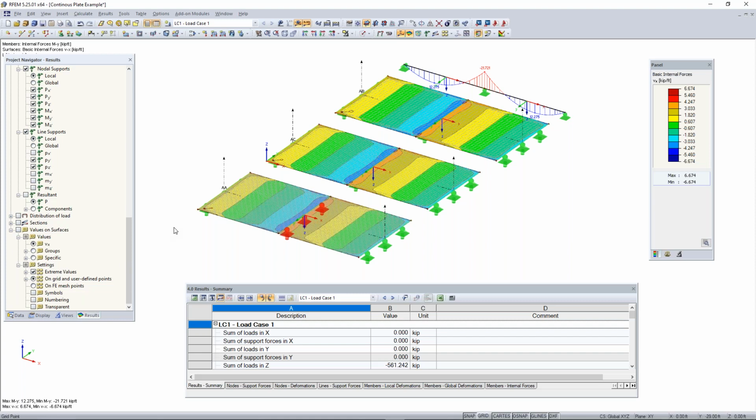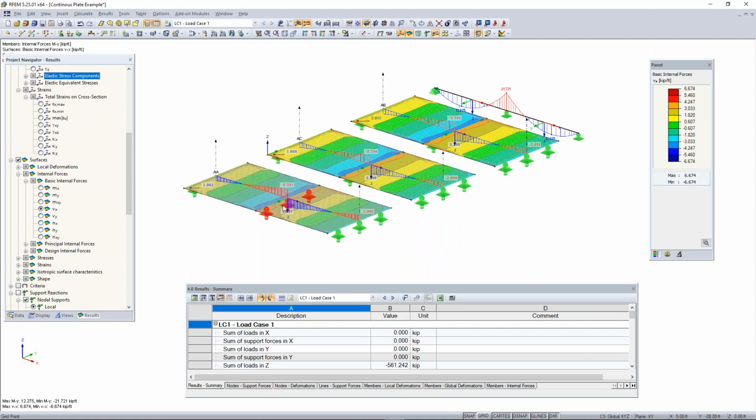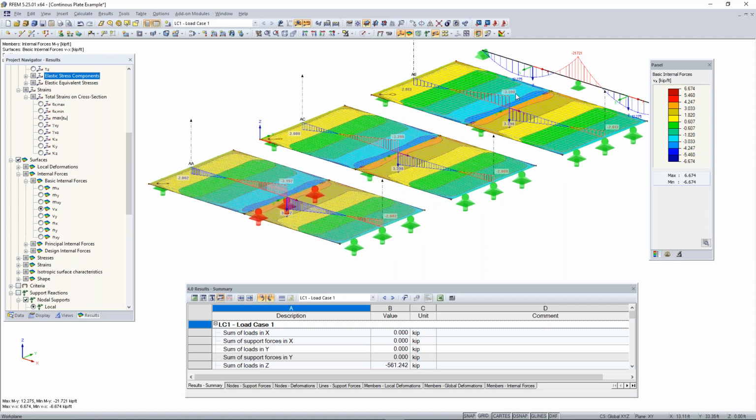So now that we've gone over the results, we can take a better look at the results and activate the section cuts here. So now that we added these section cuts along our surface, we can turn those on. And now we can basically see what the shear of the surfaces are with a shear diagram and that section cut plane. So right now, you can maybe get a better look at how those results differ from the accuracy between these different plates here.